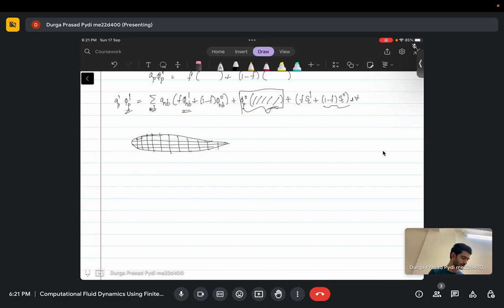And then you have other cases. Say you have a circular domain. There you can see it very clearly. When you have a circular domain, you can use a polar grid. If instead you use a Cartesian grid, you are essentially approximating these curves as straight lines, so you need a much finer mesh to solve them. Or alternatively, you can use a finer mesh only on the boundaries and make it coarse near the center. So your accuracy is a different thing; it depends on how you discretize your domain.